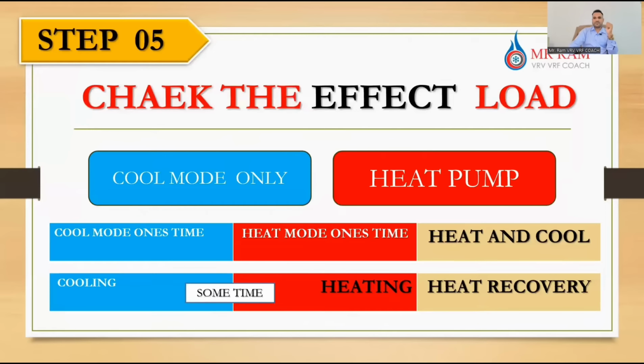After that, check the effective load. Most of the time the effective load is very important for the working performance of all indoor and outdoor units, because sometimes the quantity of indoor units is matched to the capacity of the indoor and outdoor unit, like 8 HP, 15, 16 HP. But the heat load and the load of the effect, like cooling and heat mode, both modes and the heat recovery system. We are not talking about any particular mode, heat or cool. I'm just telling you about the load of effect, cooling effect, heating effect.